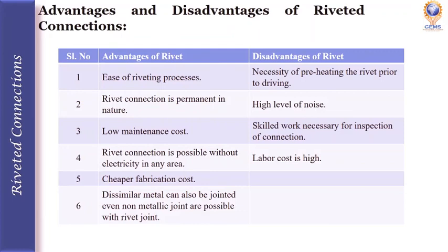And what are the disadvantages of rivets? Necessity of preheating the rivet prior to driving. Before we insert the rivet, we have to heat the rivet. So that is one disadvantage. And it will have a high level of noise. Third, we need skilled labor for inspection of the connection, and the labor cost of those inserting these rivets is very high.